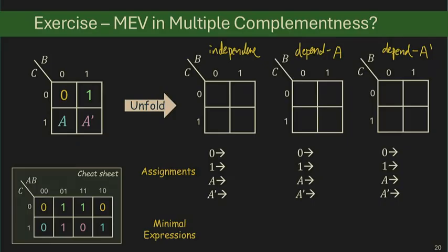Yes, sort of. Yeah, you have really folded the 6-variable function into this 4-variable K-map. And once you get to this point, we just have to interpret them into some output values. So E means output is 1 when E equals 1. So output equals E when you are at that position.